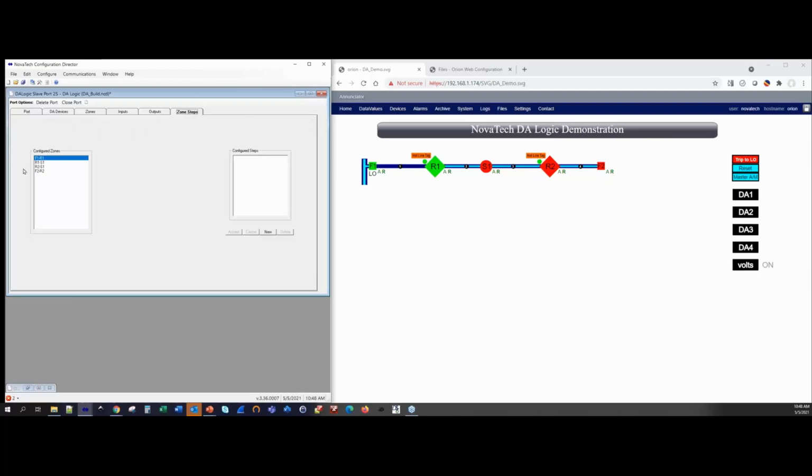Okay, so for zones, what we did right here, we had a fault on feeder R1. We're going to define those zones. The first thing that we did when the fault is here, protection already opened up feeder F1, and we had a fault on zone 1. So that's going to be the steps that we're looking at for feeder F1 to R1, that's this zone.